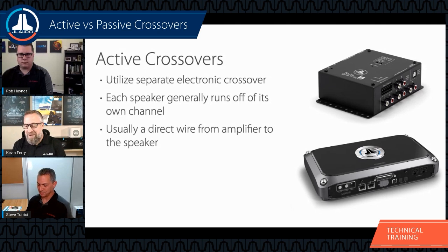I'm sure there's somebody in the chat that is asking, well, what about C7s? They come with something that goes in line between the amplifier and the speaker itself. Well, that is a cap that protects the tweeter itself, and you guys should use these and always put them in line. It is for protection only. And if you take a look at the mathematics of the cap itself, it's well below the frequency range that you're going to high pass filter the tweeter at. It is strictly there for protecting the tweeter. So make sure that you guys are using that in line.